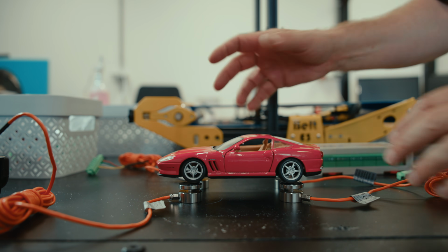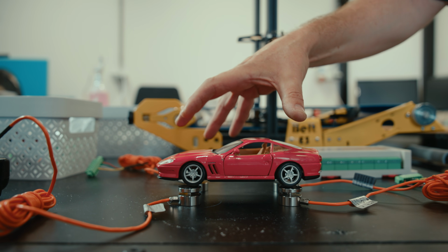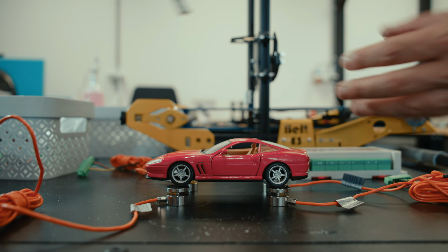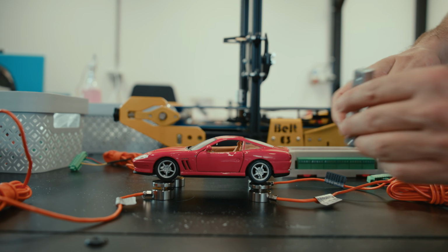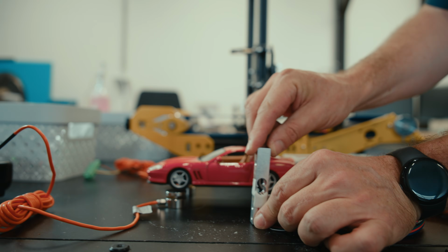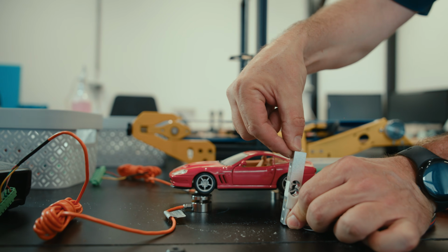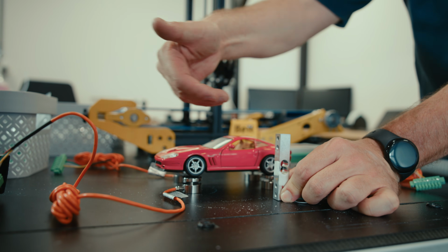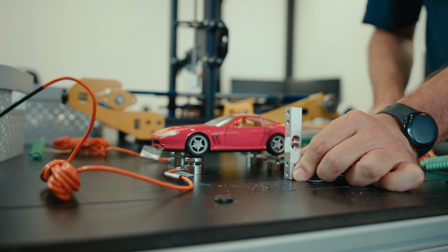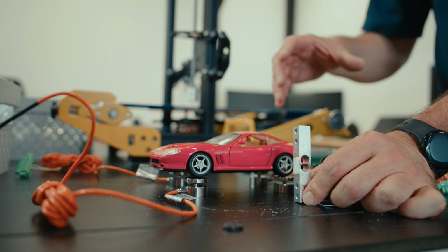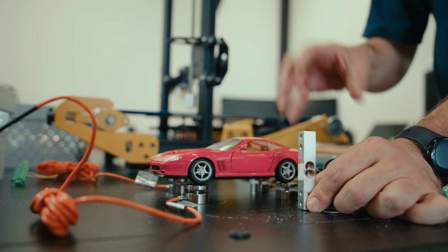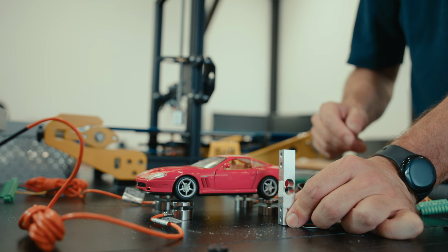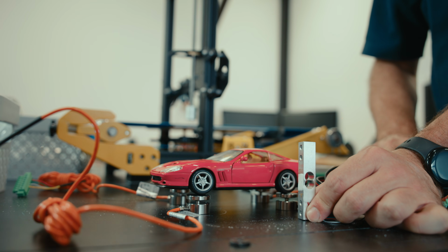Then that whole thing will be on a platform that can rotate. And that platform will be measured using strain gauges, and it will measure how much pressure is on the car or on the object we're testing in reverse. So it will measure how hard the wind pushes on the car. And that combination will give us lots of information about the design of the car, or the spoiler, or the setup, or you name it. And that will help us optimize the design.